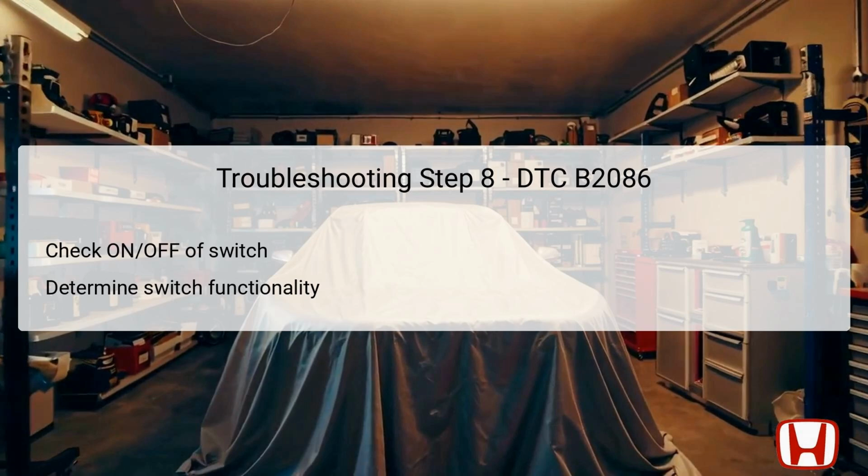In this case, the right power sliding door control unit will need to be replaced, as it cannot communicate the latch status effectively. Conversely, if the indicator does not read off, further investigation will be required. This analysis is crucial for isolating the issue within the door's operational system.